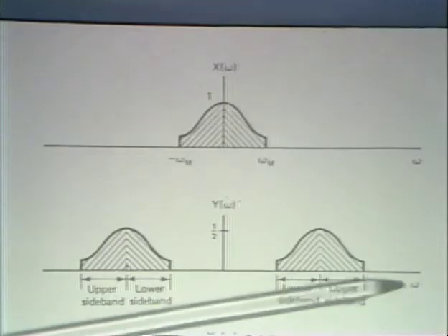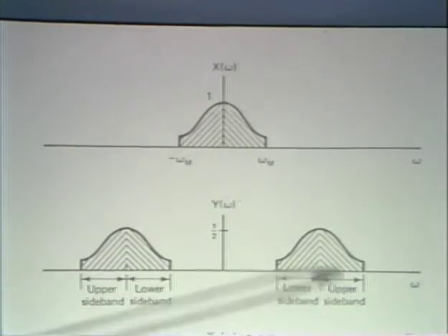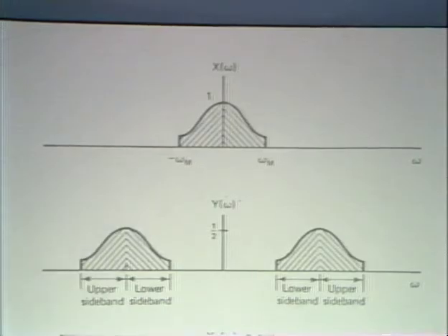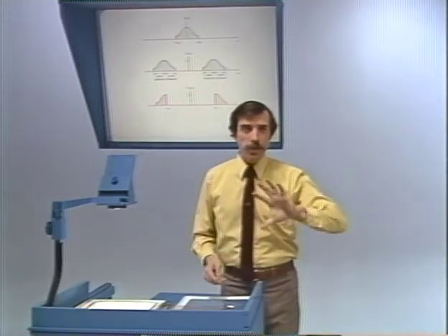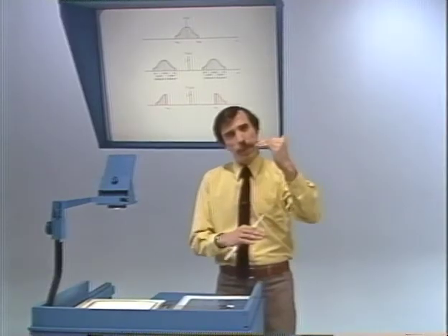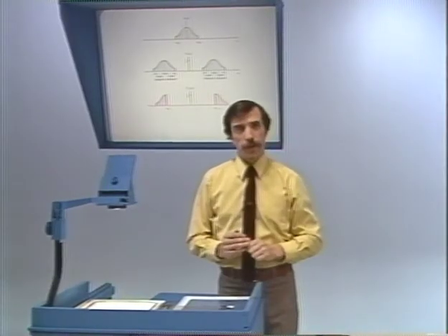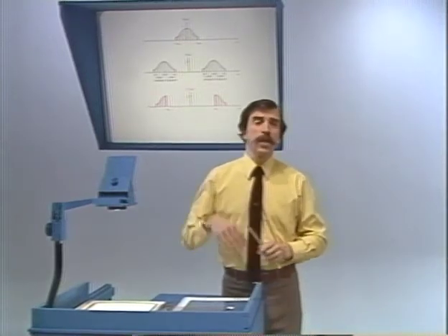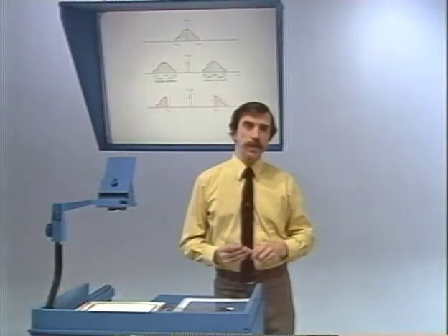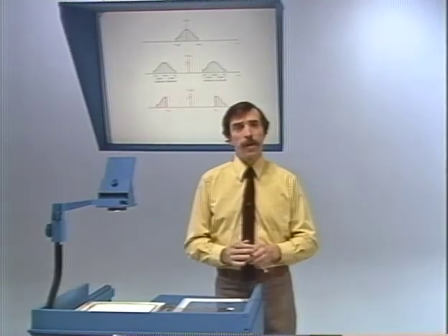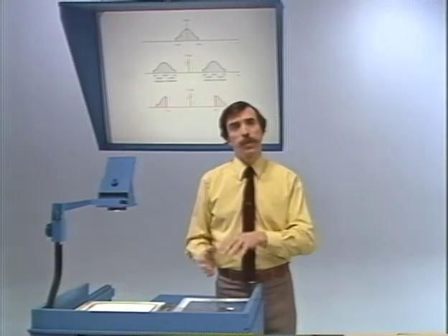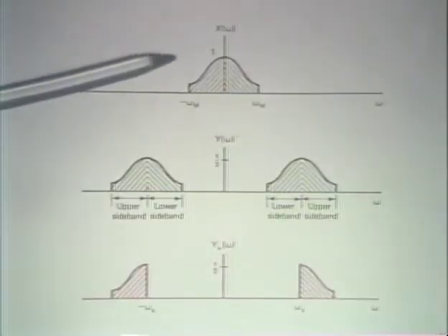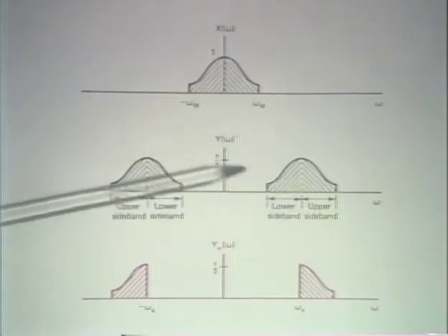Well, you could say, okay, let's just shift this up this way and get rid of this part. That's, of course, what the complex exponential carrier did. And the issue there really is that now you've got to transmit both a real part and an imaginary part. So what you can ask is, if you still want to transmit a real valued signal, how can you somehow remove the inefficiency or redundancy in the spectrum? Well, notice that what we have is this spectrum moved here and moved here.